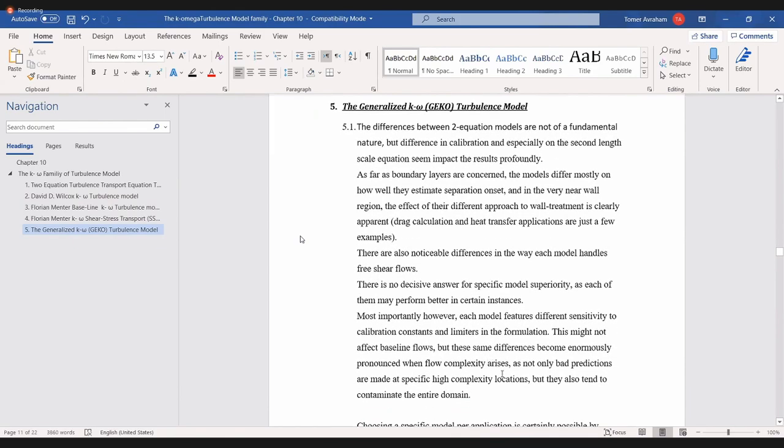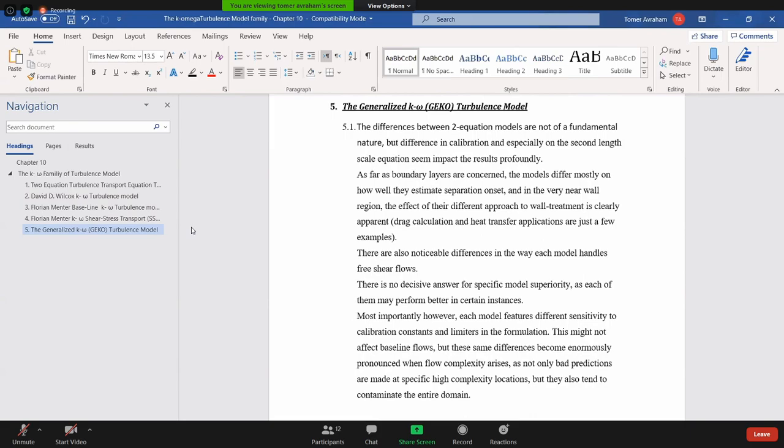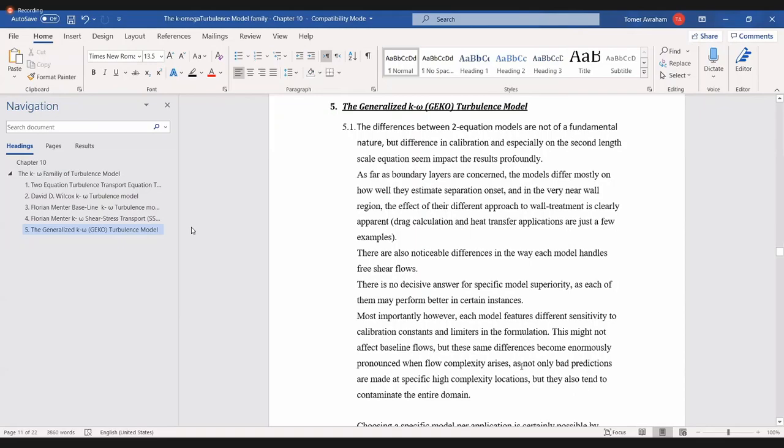It's probably the single most complex mode of transition that we have, of large turbulence intensity, the different ways of penetration into the boundary layer, non-normal modes which grow transiently, and nonlinear actions that redistribute the energy because they cannot grow the energy.